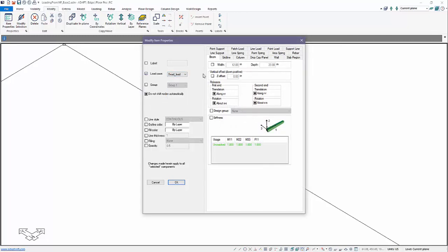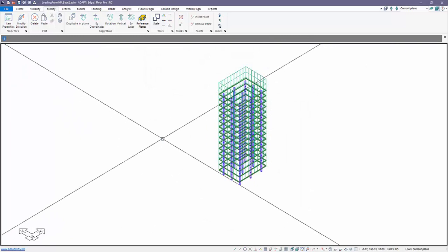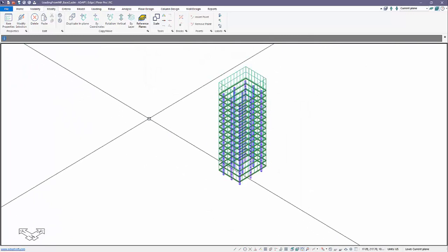I'm basically just switching out the load case name because all of the imported combinations are assigned to this name. So that's probably an easier way to handle the fact that we imported load case names and had to change it slightly, because there was no mapping of load cases when we set the import option values at the onset of this particular example.